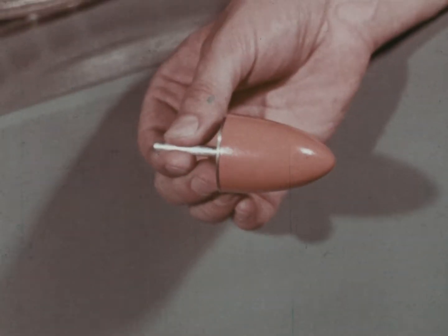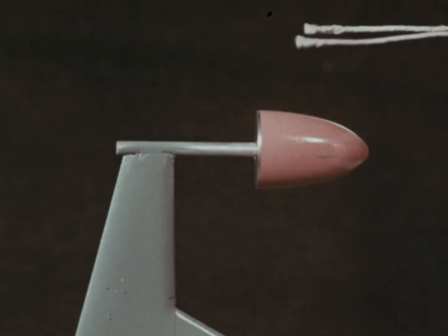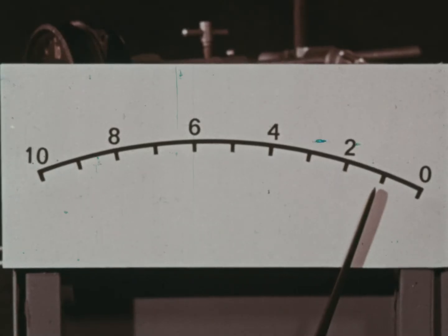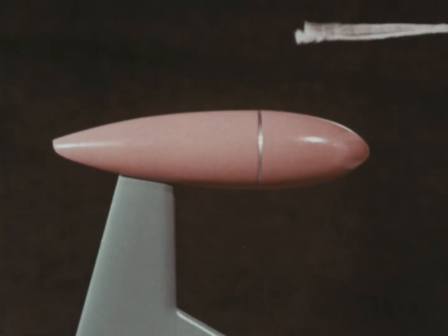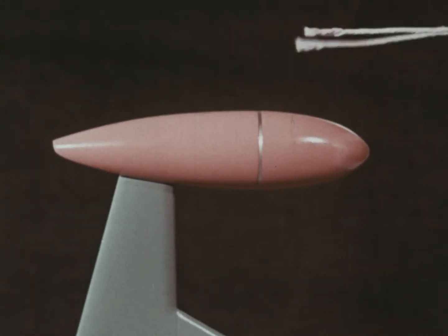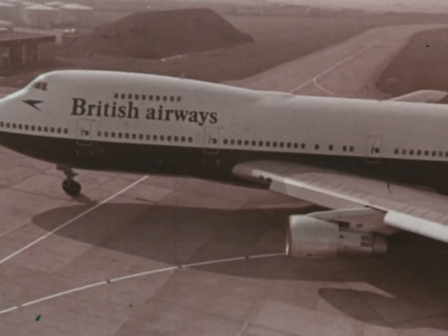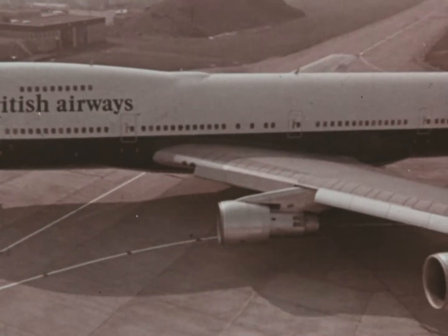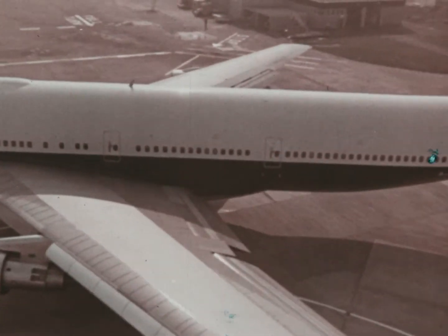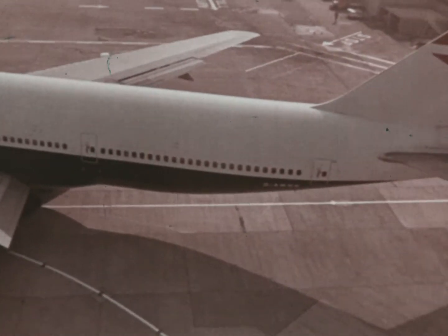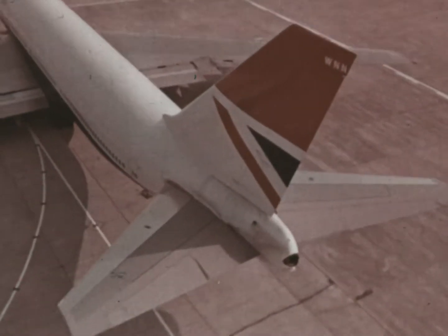If we add a bullet-shaped nose to the medium-sized disc, the drag rating at 100 miles an hour is reduced from 5 to just over 1. Add a streamlined tail, and it goes down to less than 1. The drag arising from the shape and size of an airplane is known as form drag, or normal pressure drag. And if the shape is sufficiently streamlined, the size doesn't matter so much.